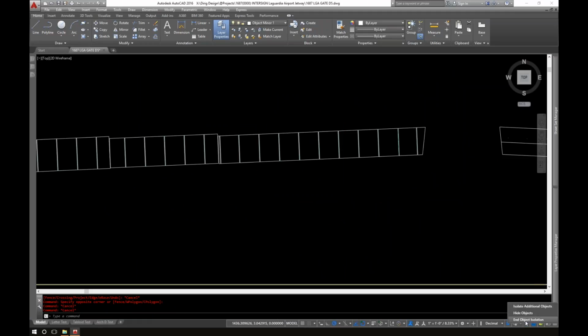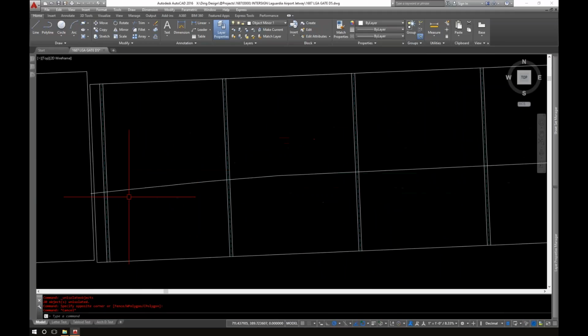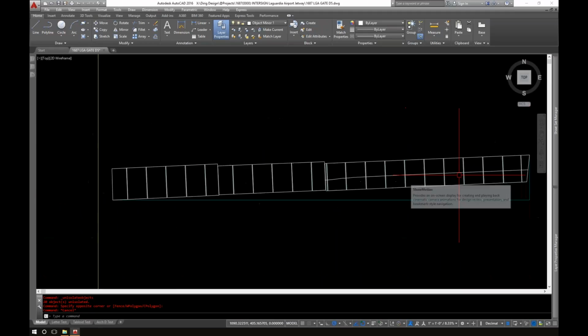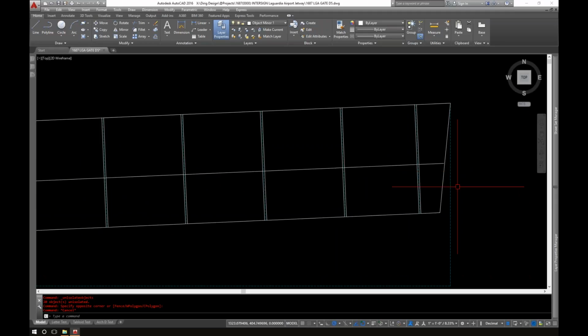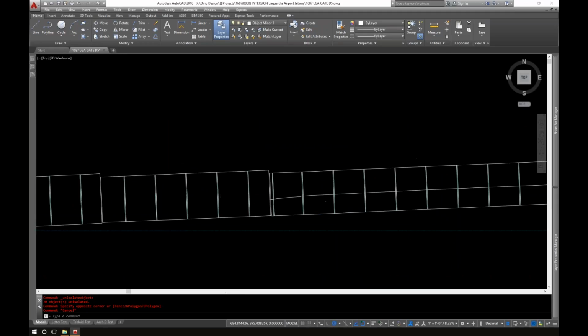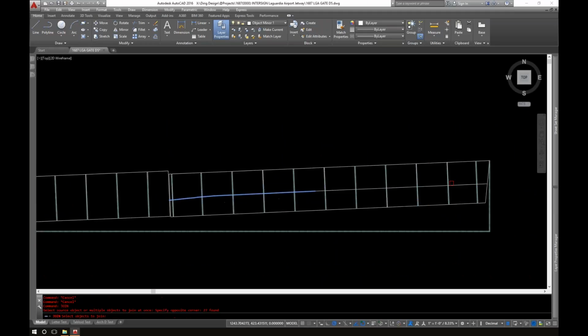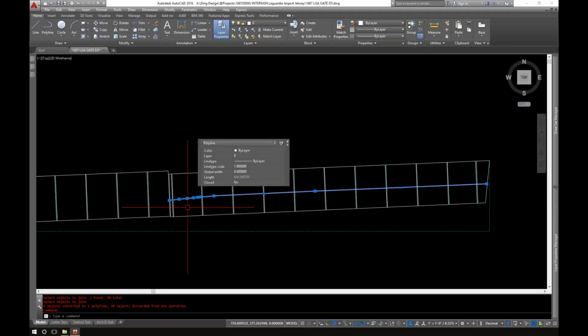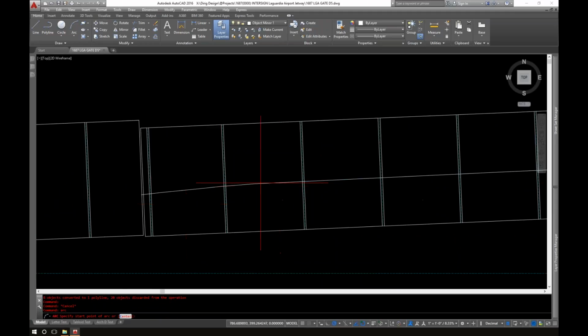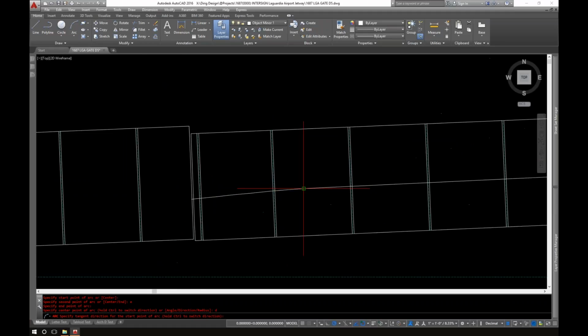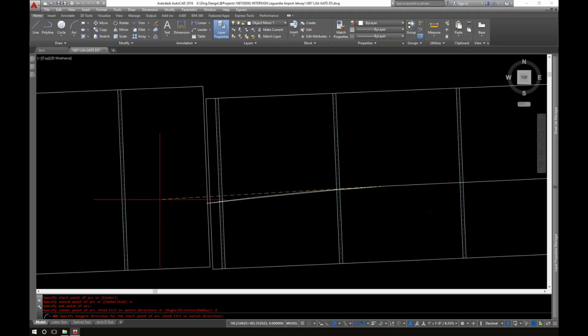Now the last thing I want to do is just end my object isolation, and the last thing you'll see here is a railing, which I'm going to draw. And we were just really concerned with the location of it. So what I'm going to do is I'm actually going to join this guy all in one shot. And the railing had a curve to it, so I'm going to start where the curve started. I'm going to hit E for endpoint down here, which was really the start of the railing, and D for direction,